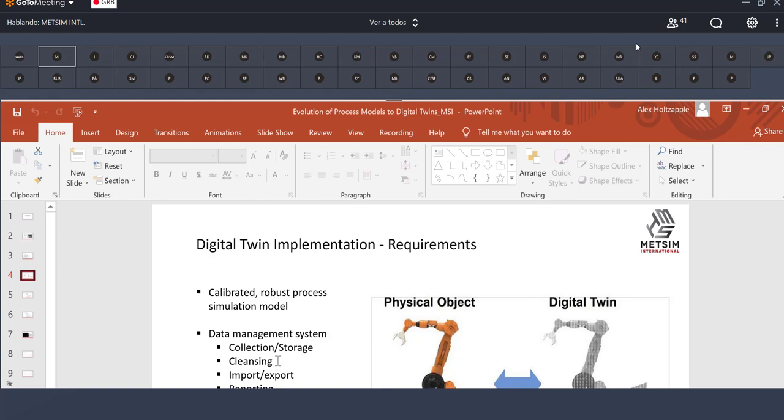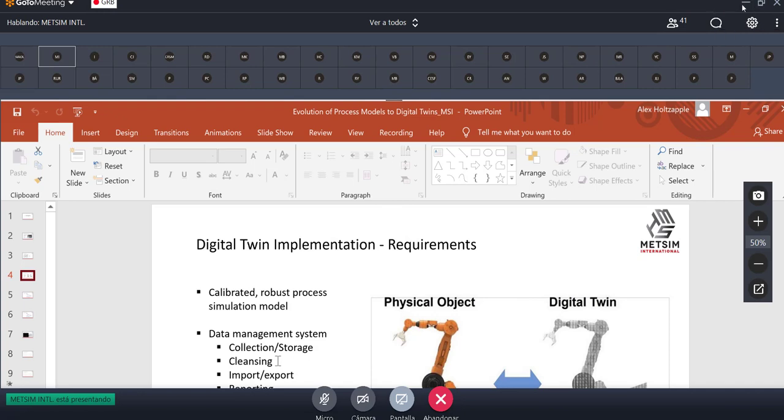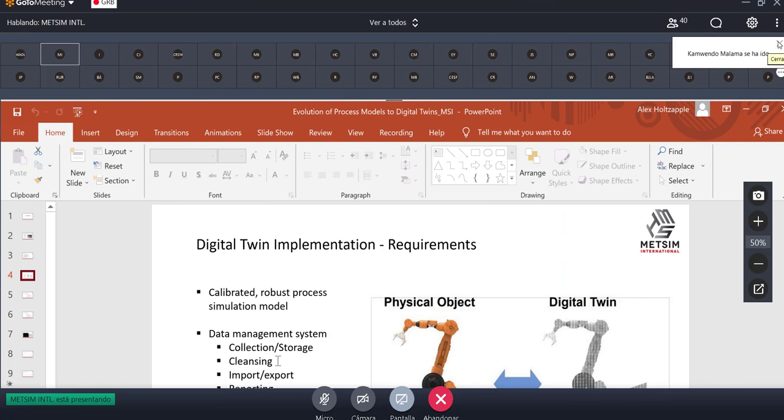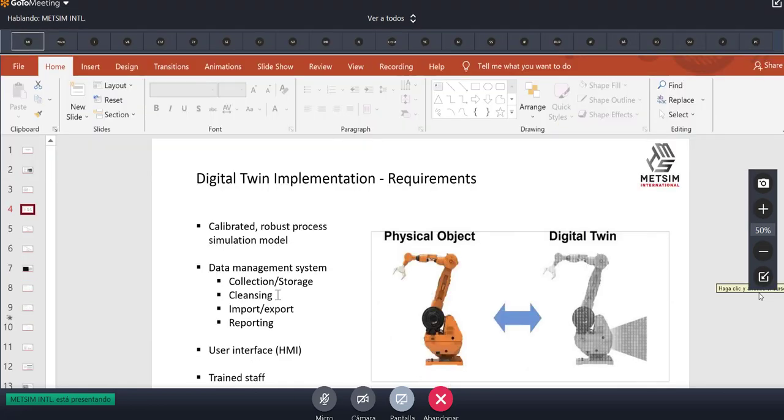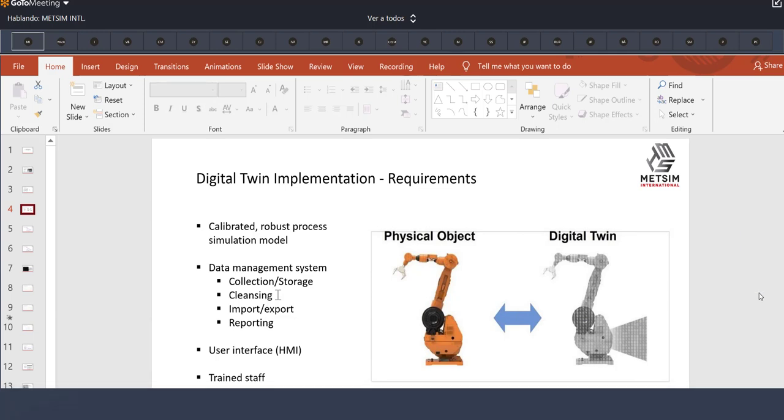What a soft sensor allows you to do is that if the digital twin has been running alongside for enough time, and you do have that quantitative faith behind the digital twin output, then you can actually start using the digital twin reading of what the pressure would be until somebody goes out and calibrates that instrument or swaps it out. This is what we call soft sensor, where if that pressure reading is determining something else within the control system, the twin is able to send in a number, which may be better than a default number.